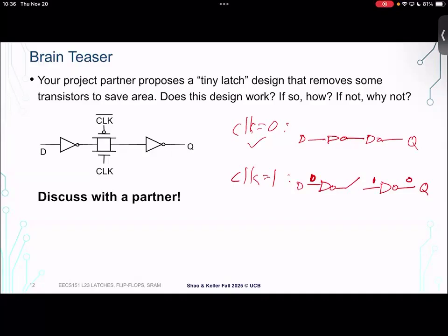So what's going to happen to this 1? This is VDD. This is just charge. If we go down one level of abstraction, there's some voltage which is charge sitting on the gate capacitance of that inverter. And it's just sitting there, right? There's no current path for it to flow away.